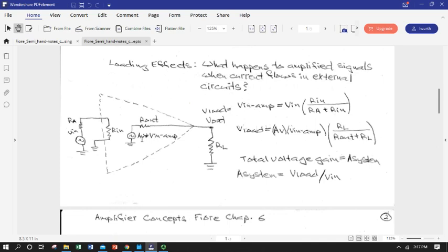It's going to multiply it by our theoretical gain, our A sub V. There's going to be a current flow, and a voltage drop over R out, the internal output impedance of the amplifier, and then of course it's going to drop over the load. The actual voltage at the output versus ground, which is what we care about, is again only going to be a fraction of what the voltage produced here inside the amplifier, because there's another voltage divider. We only get part of that.